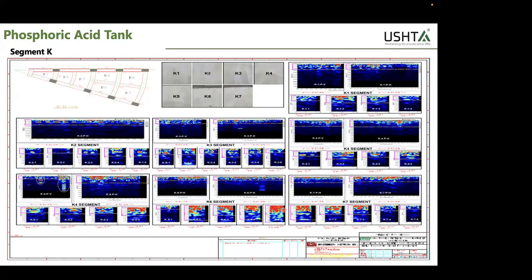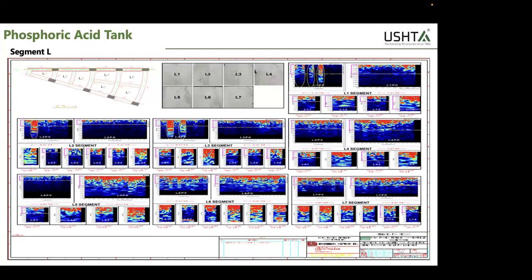Now, tomography is a multi-array thing, so it has 24 channels. It also works on the principle of sound. Wherever there are voids, it'll show red marks and the readings. It's like a slice, you see a complete slice-like image. So when we did tomography, we saw that there were huge voids, pockets, voids, piping happening inside.